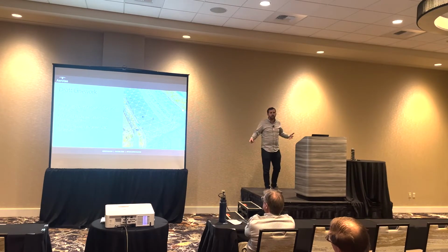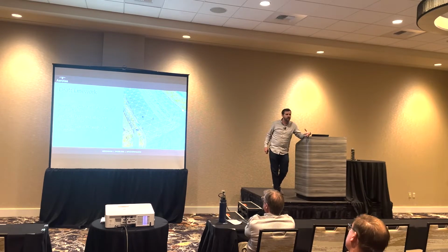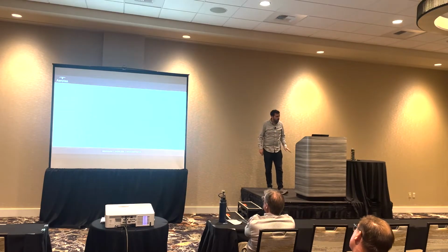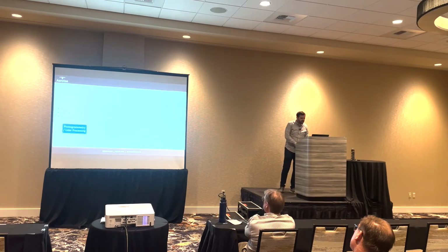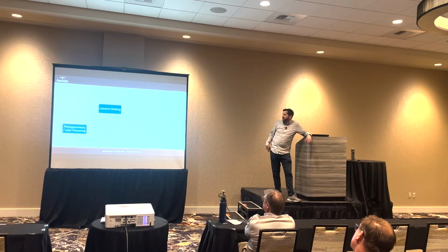Partly because raw point clouds, heck, even one classified point cloud, is still going to be way too big to actually be useful in any sort of CAD environment. And then you finish it in CAD. So, final summary, and then we'll go into even more detail, because there is an awful lot of detail. You start with your photos, ground control, RTK, PPK, go through LiDAR processing and photogrammetry, and create yourself an orthophoto, DSM, and point cloud.